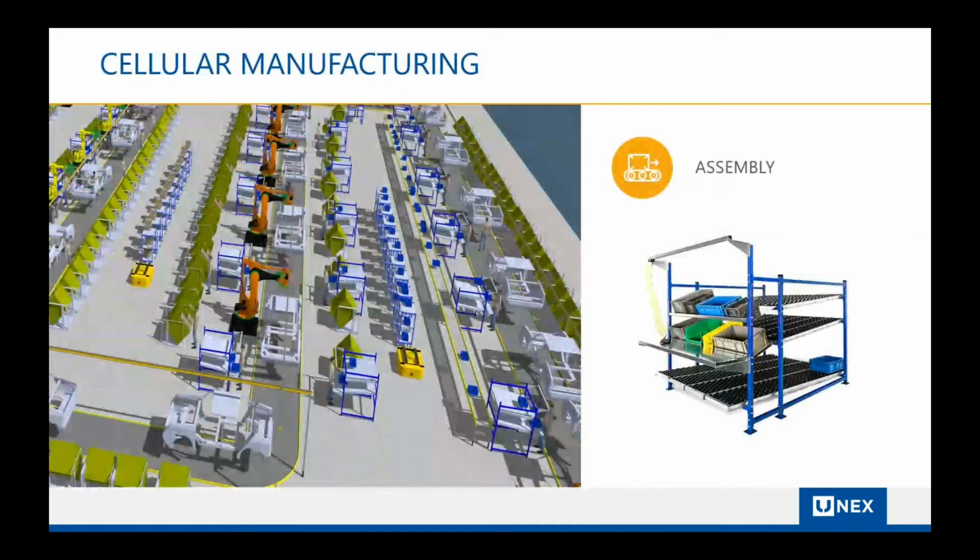So cellular manufacturing. This really now is where UNEX comes into lean, and where we're trying to put you as our customer, our distributor, in a spot where you can have conversations with the customer and feel comfortable. So cellular manufacturing is a lean method of producing similar products using cells or groups of team members, workstations, or equipment to facilitate operations by eliminating setup and unneeded costs between the operations. So the cells might be designed for a specific process, part, or complete product.